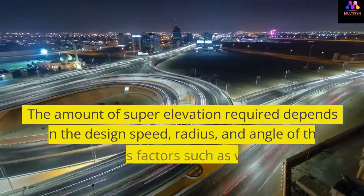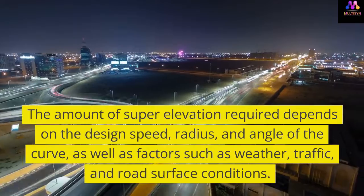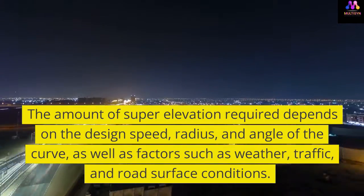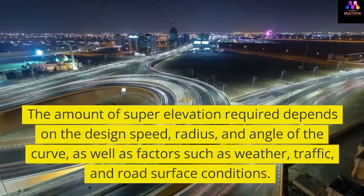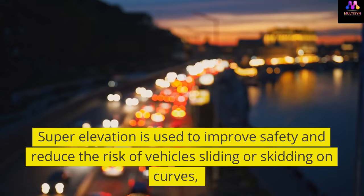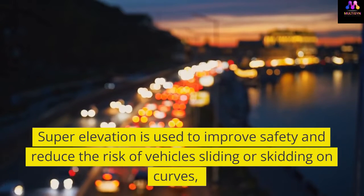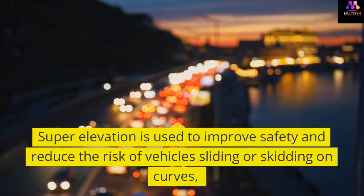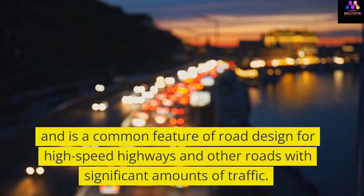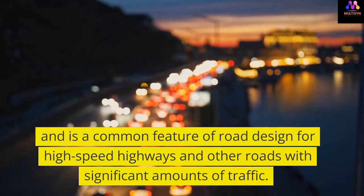The amount of superelevation required depends on the design speed, radius, and angle of the curve, as well as factors such as weather, traffic, and road surface conditions. Superelevation is used to improve safety and reduce the risk of vehicles sliding or skidding on curves, and is a common feature of road design for high-speed highways and other roads with significant amounts of traffic.